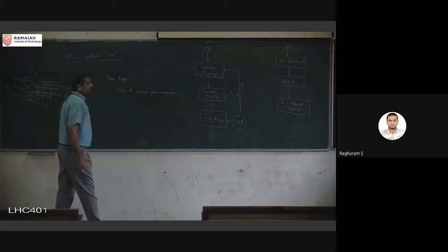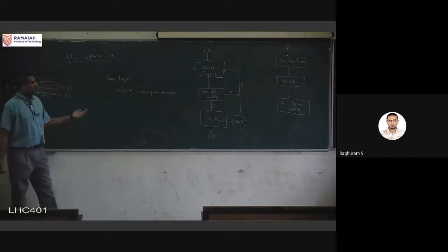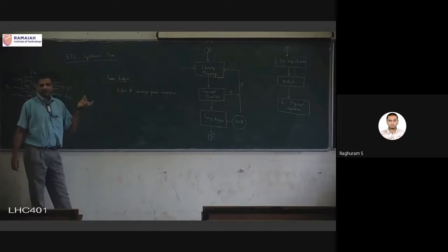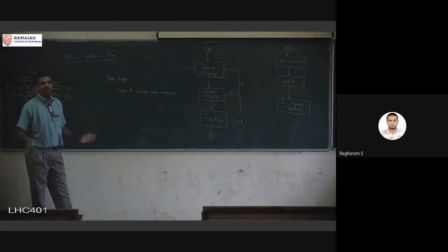It's just the analysis of average power. This is not anything high tech. We have the netlist, and based on the library data for each cell or for each gate, we have the power information. Just add it for the whole design.